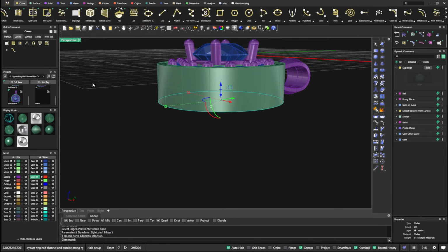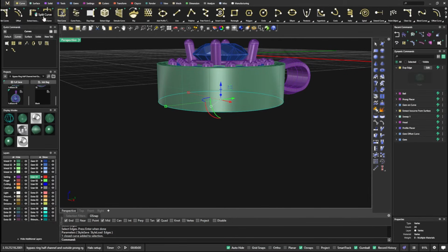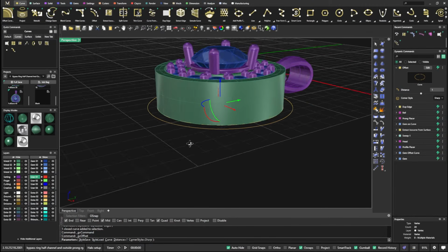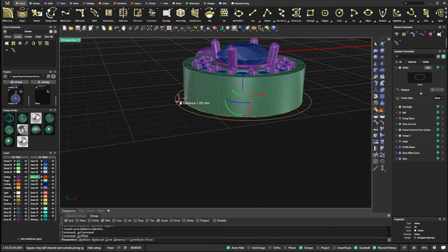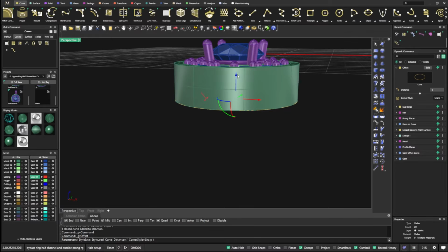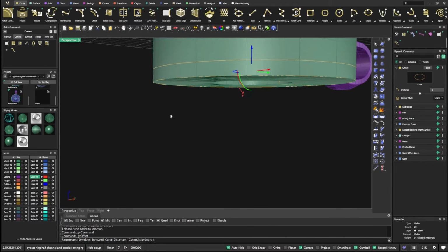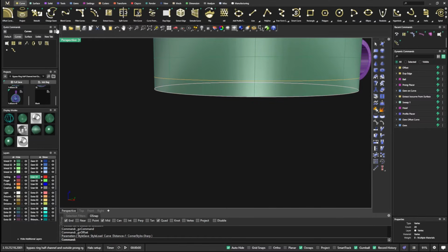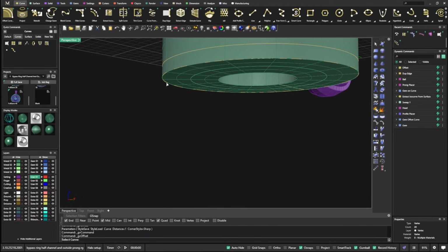No, okay. So let's grab that and we'll go to our offset curve, and we'll take this to a 0. So it's at a 0, but we'll take it up 0.8. So now we know that that's a 0.8. We're going to go back to this curve. I don't know if it'll let me do it again. Let's see. Offset curve, select curve, this one.